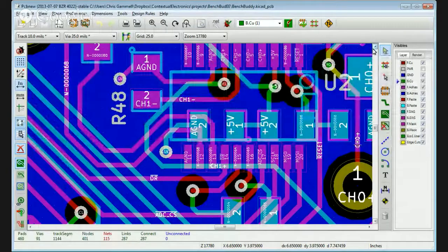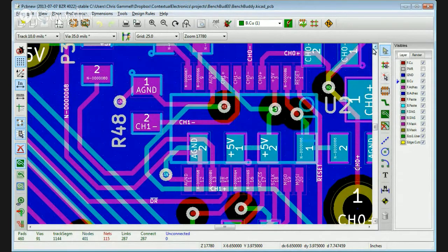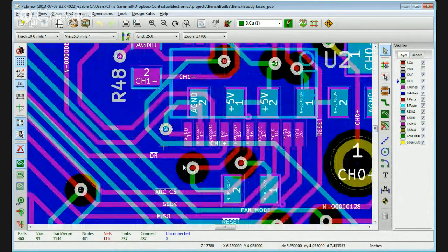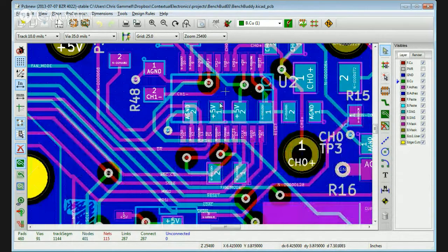Yeah, yeah. We put enough test points in too. Speaking of the vias, we probably should have tinted these vias as well, and gotten some solder mask over them, just because we had people trying soldering for the first time, stuff like that. I personally had problems with this trace right here on my board where I started having the solder mask lift, and this trace right here is now exposed copper. And it was really close to these pins, so basically that board was done for.